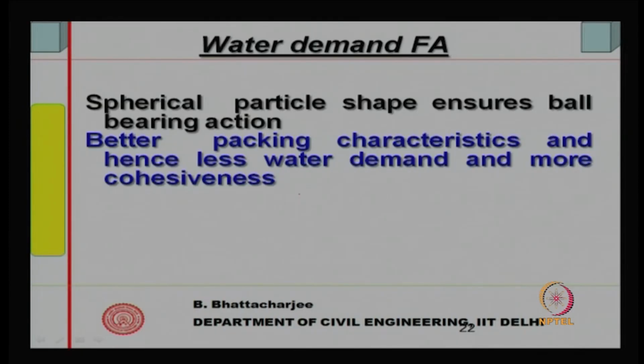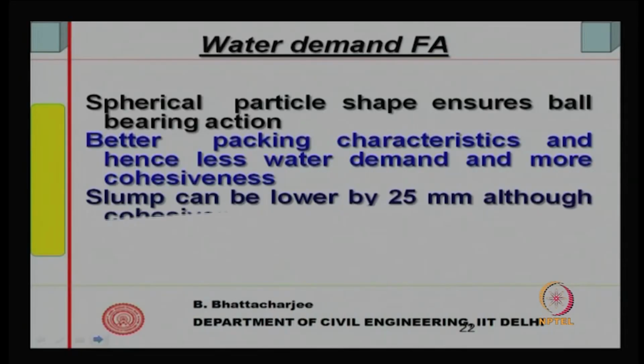So, water demand reduces because of better packing and also ball bearing action. They make the concrete or mortar somewhat flowable. So, in a way, water demand reduces with fly ash. Slump can be lower, although.